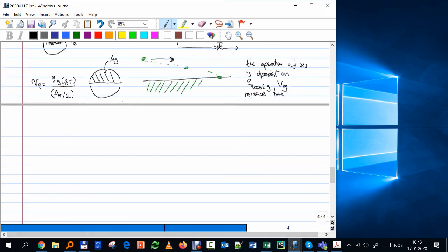So let's say in the two situations you have the same QG, right? That's standard conditions rate. That is similar to having a constant mass flow of gas, right? If I say constant plateau, 20,000 barrels, or 20 million standard cubic feet if it's gas, that is the same as saying that the mass flow is constant. So in one situation, how do you calculate that QG in the separator? You have P separator, T separator, that will be equal to that mass flow of gas divided by the density of gas at that particular P separator and T separator, right?